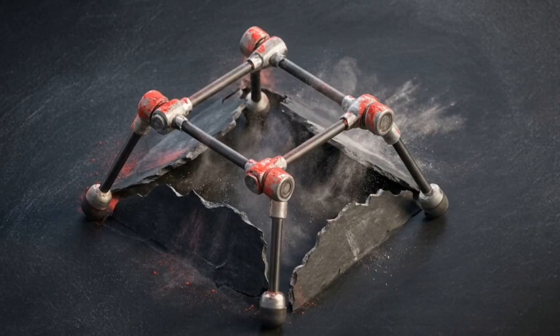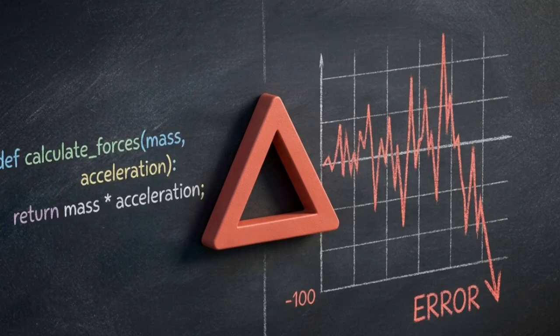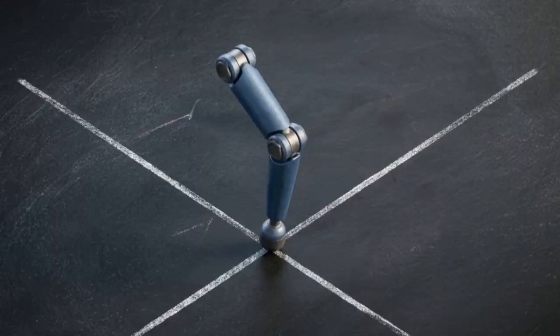The transition from stance to swing phase becomes a struggle, causing a jerky, lurching gait that drains battery power and destabilizes the body. You can spend months writing a perfectly balanced gait controller, but if the ground contact parameters in your physics engine are improperly tuned, the controller will fail.